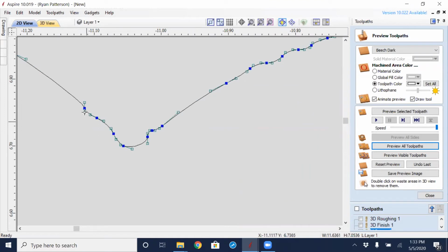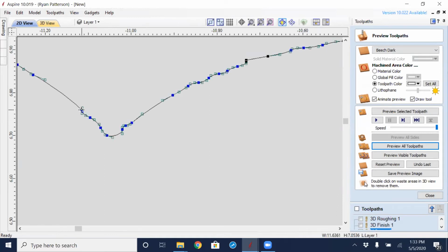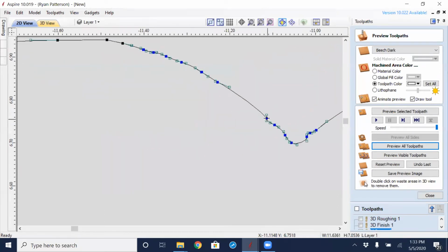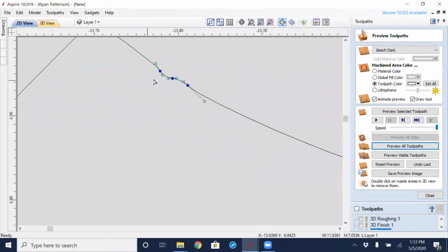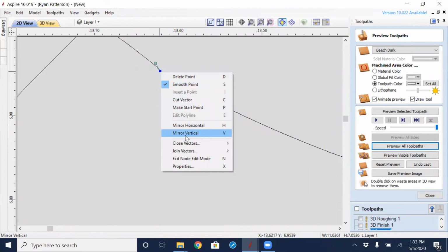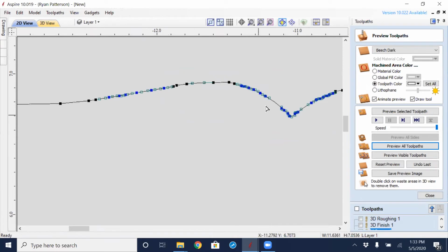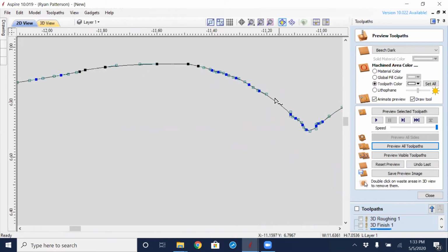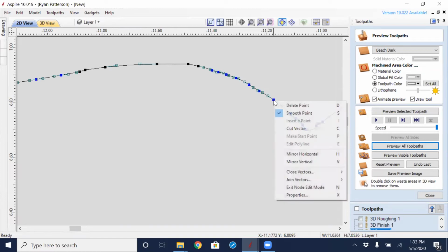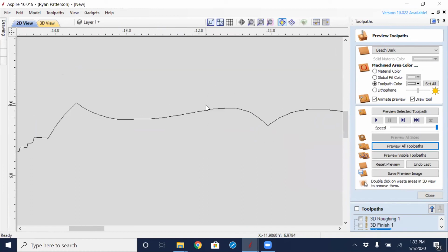So I'm going to break this apart simply by hovering over the node where I would like to cut it, right click and select cut. Come back over and try it on this right side again. It wasn't liking that. Just insert a new node here and try right clicking and cut. So now that allowed us to separate one from the other.